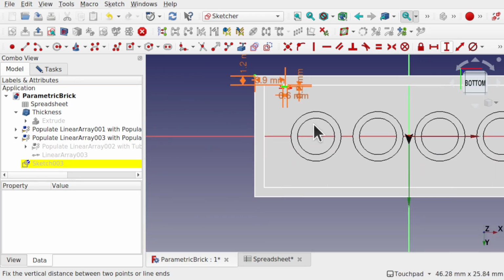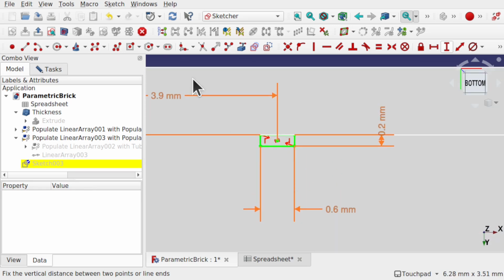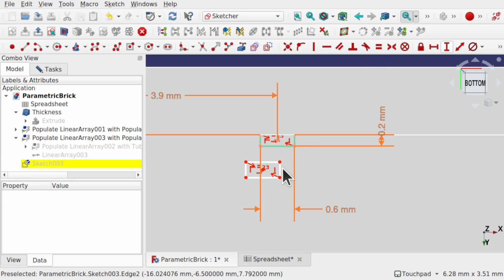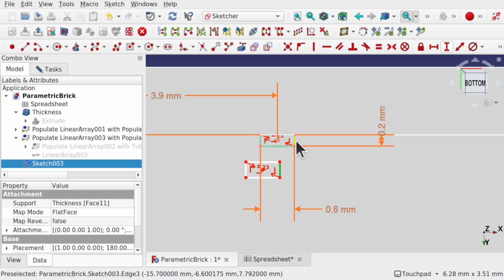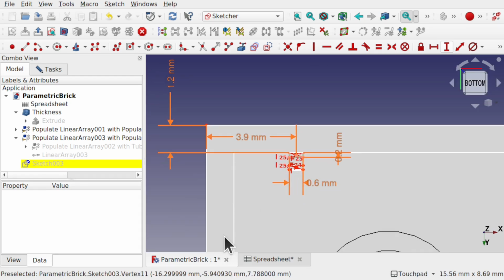So we're going to create basically a mirror of it over here. To do that, I'm just going to sketch straight into this sketch here by using the center rectangle. And we'll place one in here. Now to cut down on datum constraints, I'm going to take some equality across the bottom lines, make those equal, and do them across these vertical lines as well, make those equal. Also going to take this point and put those in line.